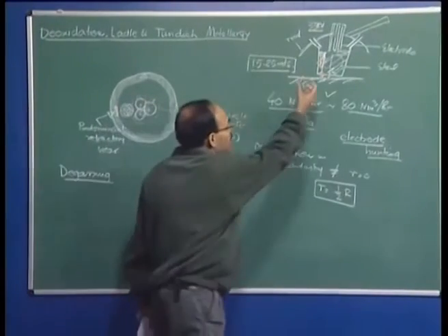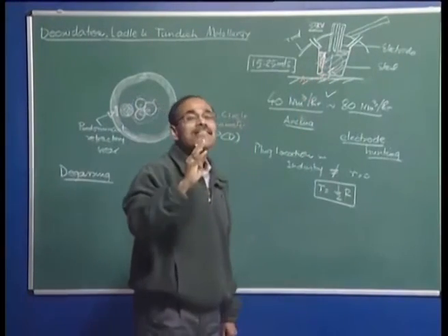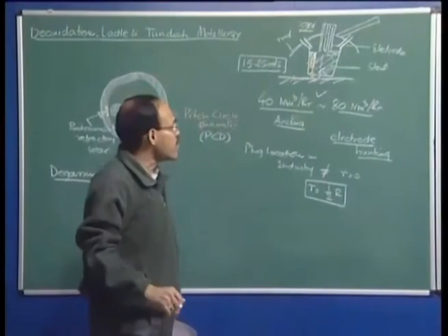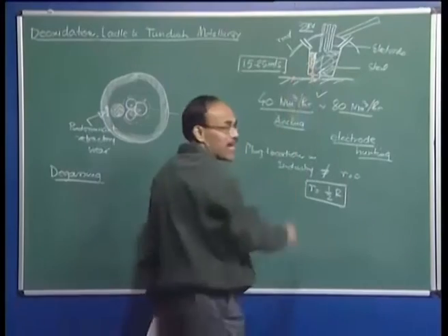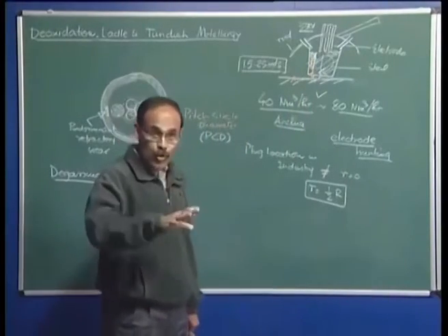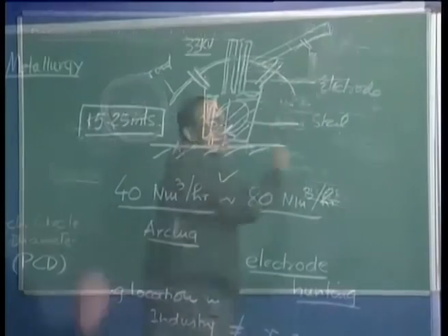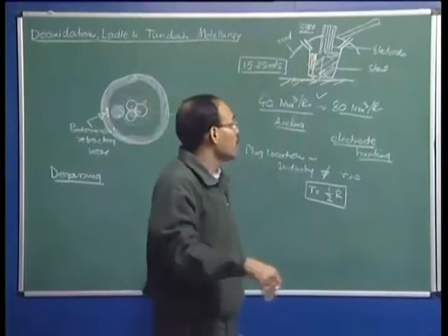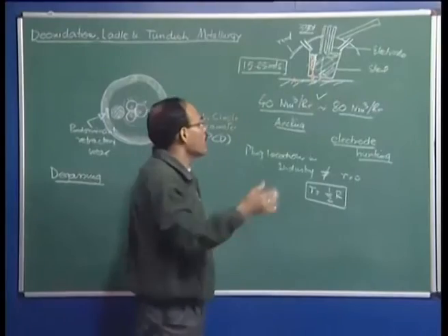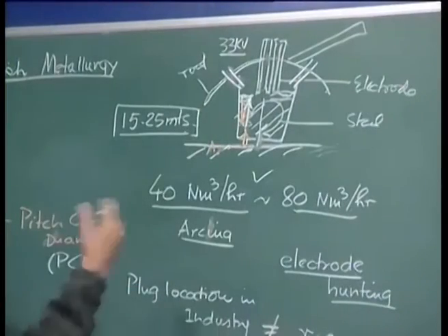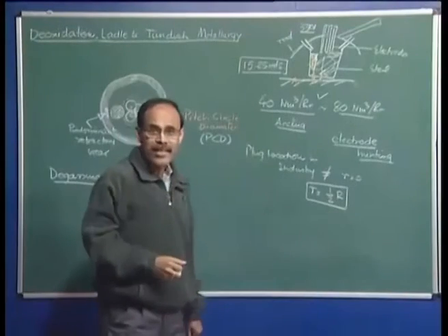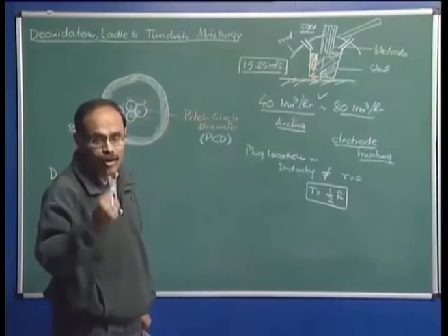So, when you get the material out of the ladle furnace, it has a little bit more temperature than is desired at the casting station. Its composition is correct in terms of solutes, but it may still contain nitrogen which may have been absorbed during tapping of the furnace itself, and hydrogen which may have been absorbed because of some wet material, like for example, the lime that we have added to make the slag. The lime may be hygroscopic in nature, being hygroscopic it can contain a lot of moisture.